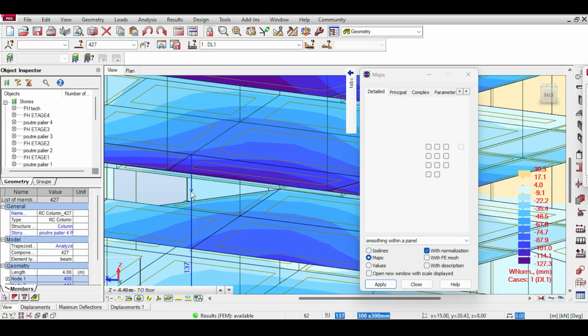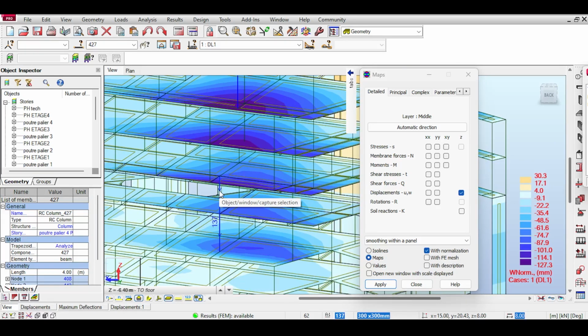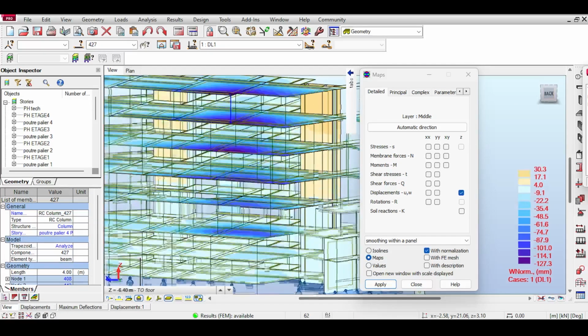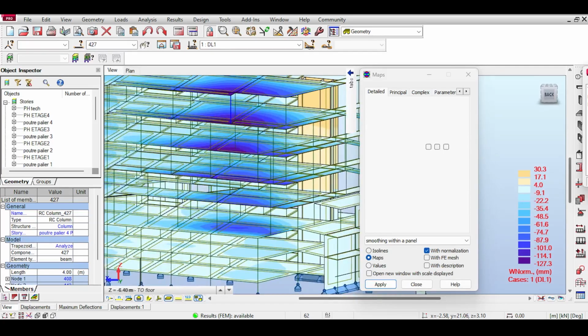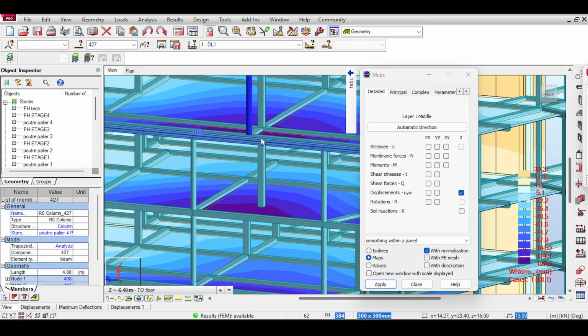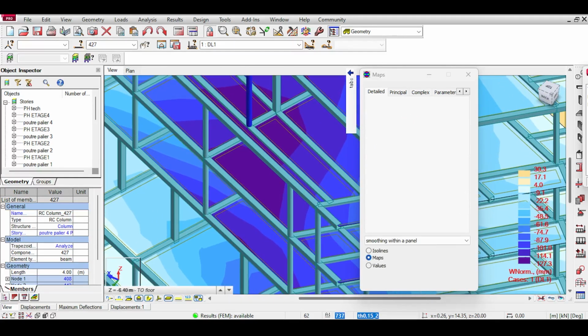Okay, there is a discontinuous column. Why is this column discontinuous? I have problems with the structural drawing. I have massive problems here. You know what I will do? I will ignore this for now, and this column's, wait, is it discontinuous? Oh my god, everything is discontinuous here. So this column is discontinuous. This column is discontinuous. And it falls on this beam, which in turn is carried by those two columns. It's not carried by anything.